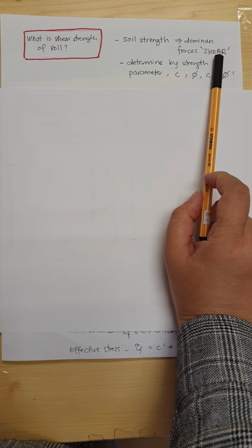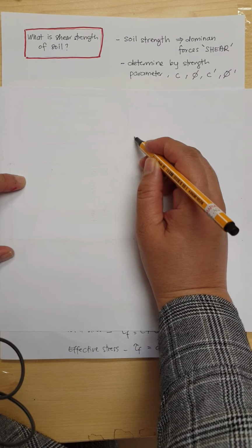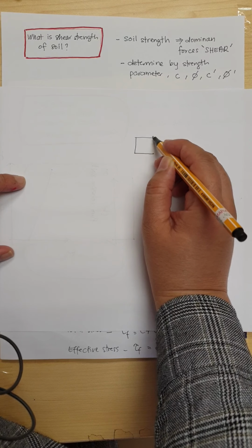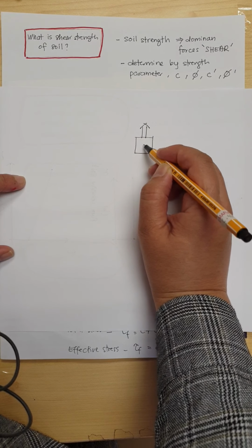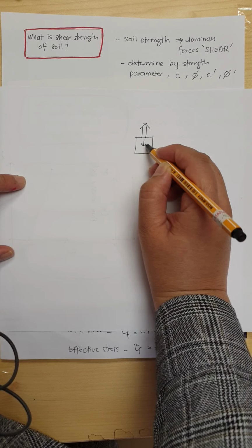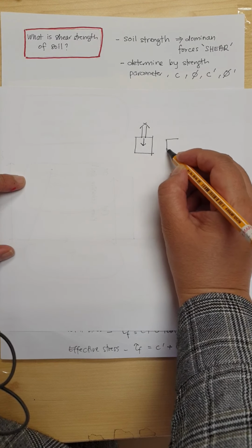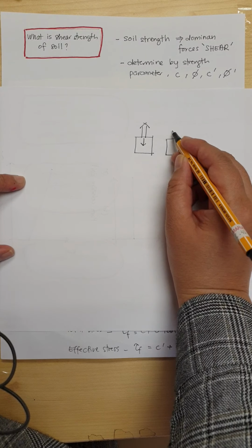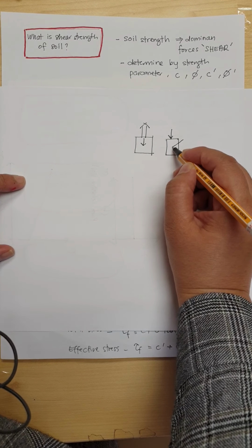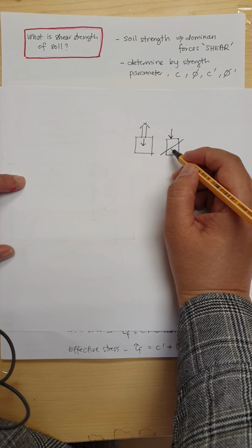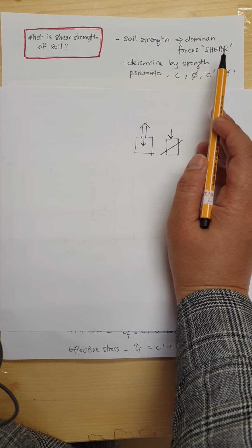This is the dominant factor because in soil, what usually happens is you have soil beneath a building. Let's say this is your building, and this building will put a very huge load on the soil below. When this is referred to the laboratory session, we simulate the same situation. So this is the load from your building. What will happen is we have failure in terms of shearing force rather than compression and tensile, so it is more dominant into shear.